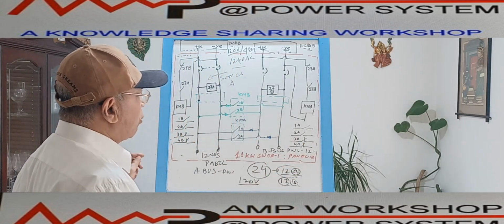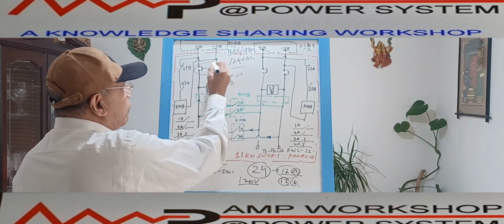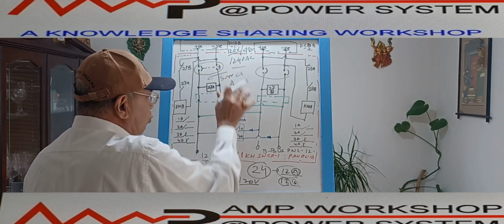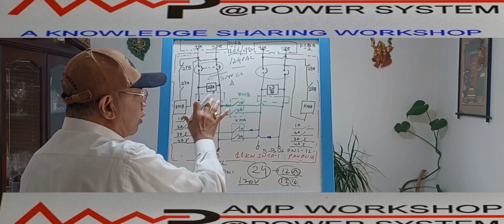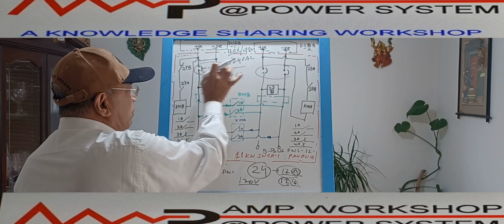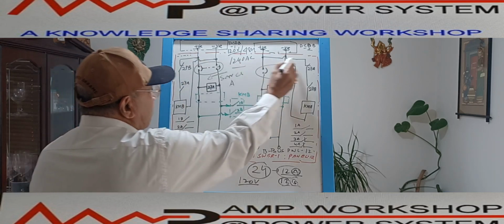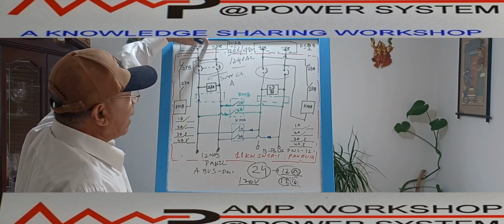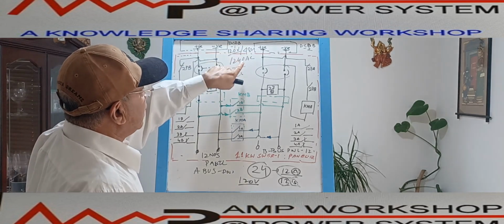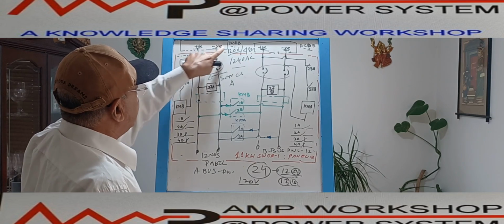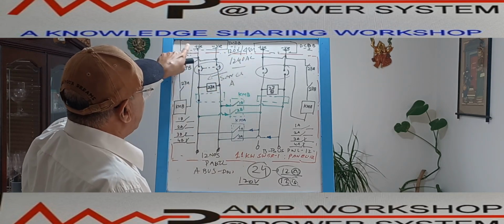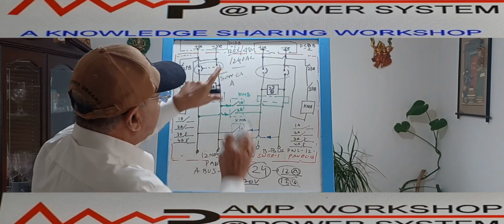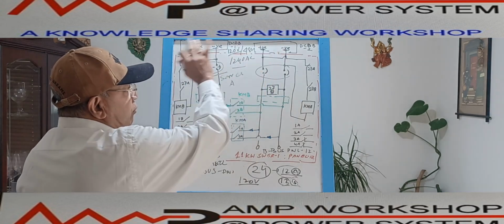Normal condition, what is happening? This is the MCB, of required rating as per the power requirement. This is in switchgear A, in one of the panels of the switchgear, where these MCBs are located. Now this red color part is inside the switchgear. This power supply is coming from the DCDB or ACDB as per the requirement. In case of AC power supply, this will be the ACDB. In case of DC power requirement, it will be the DCDB of the respective voltage. So this is DCDB1 and this is DCDB2. These are two independent sources. There is no relation between these two at the top.